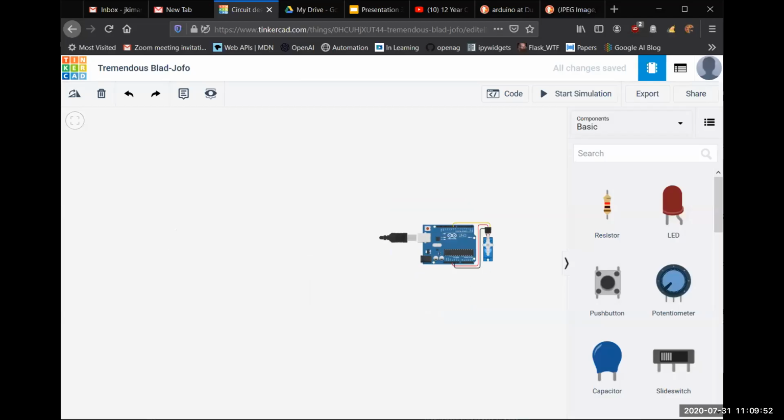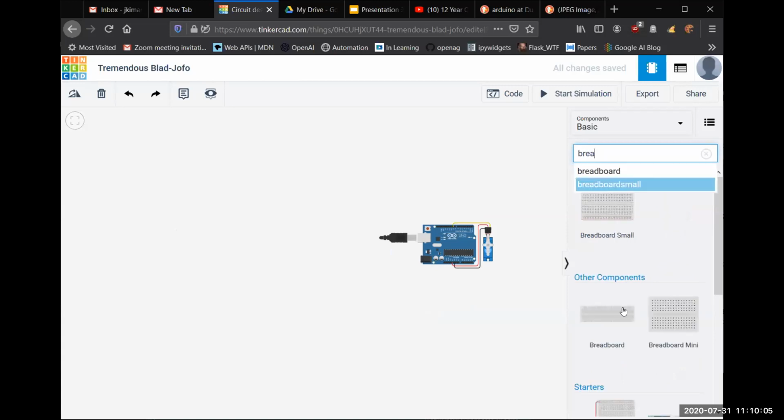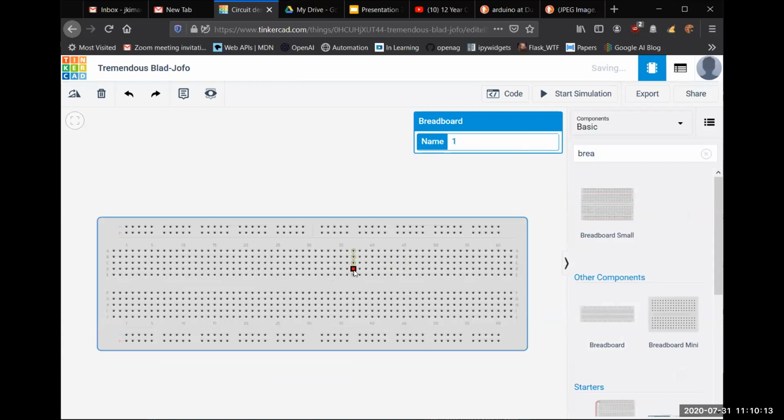For Vin, maybe just let me answer your question. So for the breadboard, it usually has numbers. They just help you to at least know which row you're using. The breadboard we are using is similar to this one here. The good thing is the simulator I'm using actually shows you how the connections are done. The ones at the top, these ones here, connect all the way straight to the end, and these are the ones that we use as power. These are the power pins or power lines. So you can just connect the 5 volts and the ground here. Minus is usually ground and plus is usually positive.